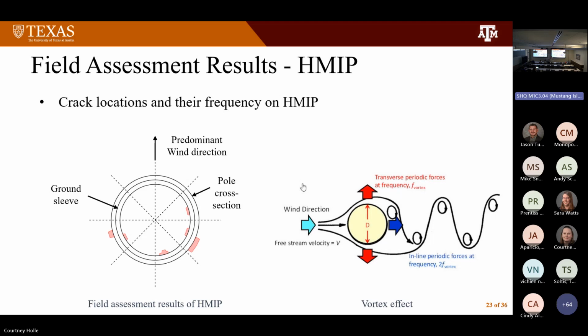And then you find out, no, a lot of it's actually caused more by vortex shedding. During a windstorm, we have a certain number of those throughout the year, and may have larger stresses. But what we found with a lot of these is that there's a little sweet spot where it sets up a resonance in these poles. It's usually around 6 or 7 miles per hour, which is always where these things are going.